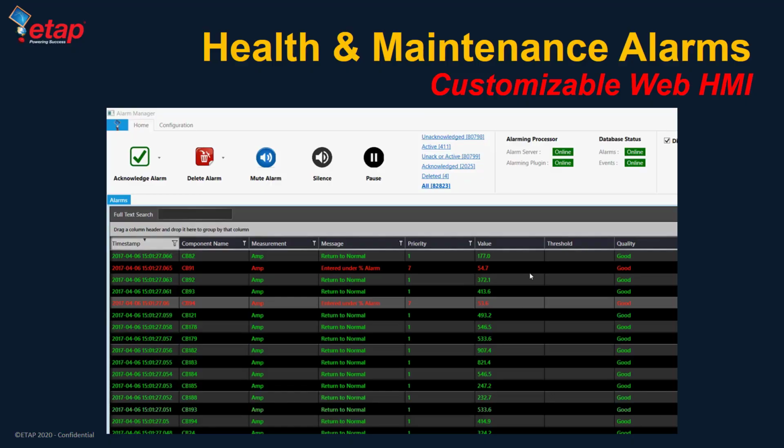Another important tool is the alarm manager. Through the alarm manager, the operator dispatcher can be notified of any abnormal condition, from the communication network to operation in the microgrid. In addition, alarms for maintenance can be built in for understanding when a component needs servicing. The configuration of the alarm system is performed at the ETAP SCADA integrator and downloaded to the controller.